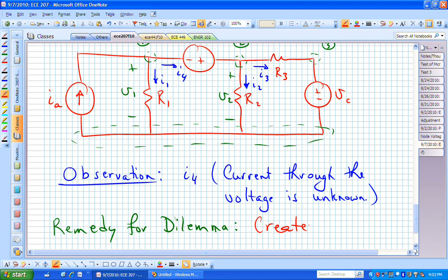Does charge accumulate at that node? No. By KCL, the sum of the currents have to be algebraically equal to 0. So now if I just enclose a lot of my circuit into one thing, a big supernode, coming out of that supernode algebraically all my currents have to sum to 0, right? Because I can't accumulate current even in that supernode.